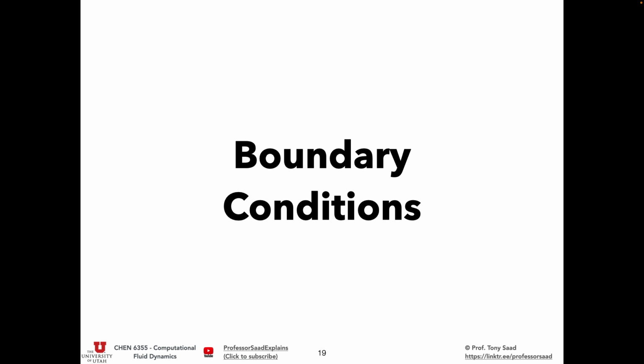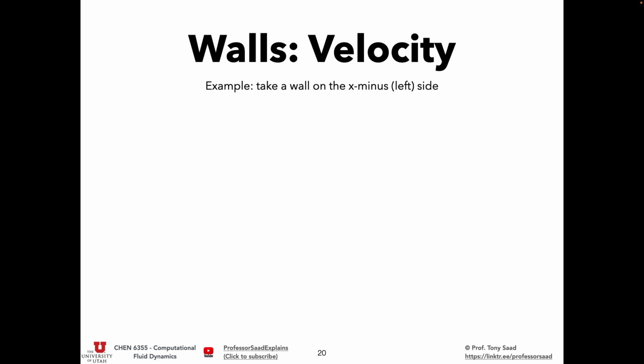You'd need to derive the conditions for inlet boundary conditions. What it boils down to, in the end, is that we want to put boundary conditions on the transported variables, which are the velocities. Even if you say, I have a pressure boundary condition, well, there's no such thing as a pressure boundary condition. In the end, that implies something on the velocity. You have to figure out how to connect that with the velocity boundary condition, and we need to tie this in with what that implies on the pressure equation as well.